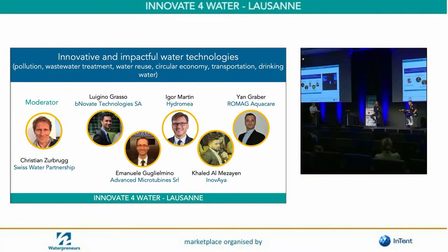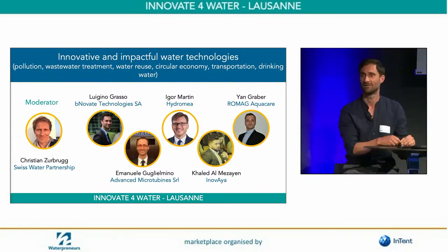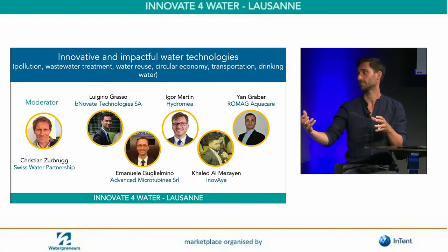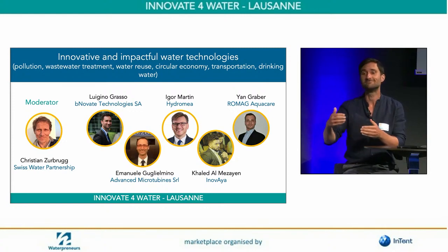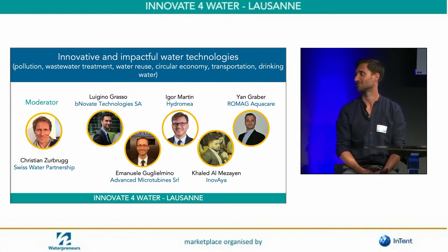So basically, as I said, it can be installed almost anywhere, really from the water catchment, to monitor the raw water. Then in the water treatment plant, after filtration processes or after disinfection processes, and then directly on the water network, either close to a reservoir or as close as possible to the customer.